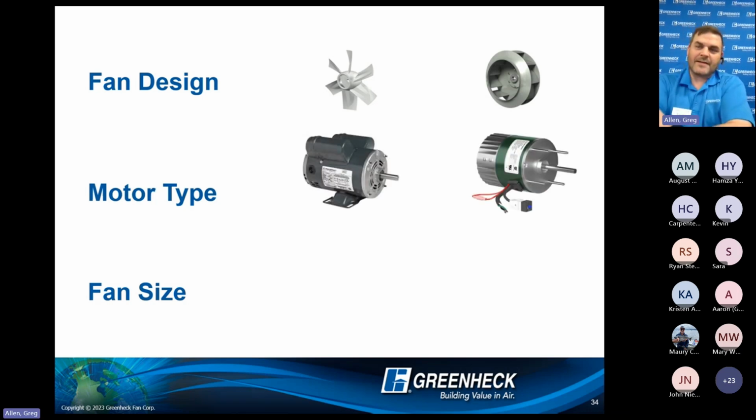But then there's motor technology as well. In the single phase world, this is very evident. If I have a single phase AC induction motor, the motors are not very efficient just by design. So in that realm, I'm showing on the screen an EC motor, or electronically commutated motor, which in single phase is sitting at 85% efficient. It's an extremely efficient design.